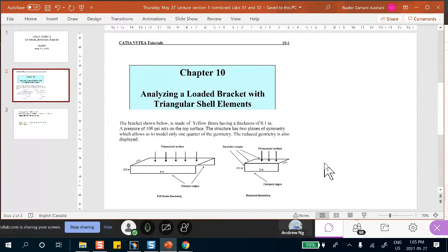Now, just like you did with the solids and beams, if there are any planes of symmetry, you have to take it into consideration. When you think about this problem, bottom clamp, same thickness of the wall, everything, and you pressurize it, if I took 1/4 of that, which is shown on the right side, 1/4 of this folded sheet metal, the behavior in the remaining 3/4 is identical.